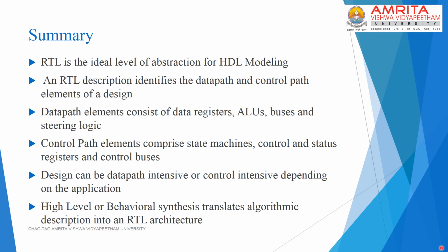An RTL model identifies the data path and control elements in a design. The data path elements are primarily involved in the flow and manipulation of data, and they comprise components such as registers, ALUs, buses, and steering logic such as multiplexers and demultiplexers. On the other hand, the control path basically controls the flow of data through the data path.